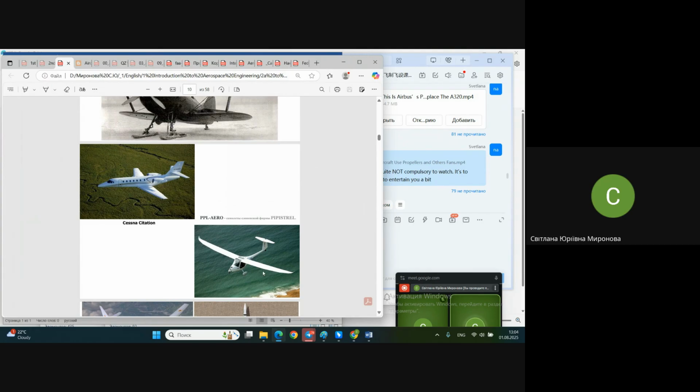How to increase the stiffness? Make the inner elements heavier. Make them more massive. Make them thicker. In case they are thicker, they are stiffer. But in case they are thicker and more massive, they are heavier. The circle is closed. In case they are heavier, we need more area of the wing, we need more fuel, and so on. So it seems it's not an ideal decision, it's a bad decision in this case to increase the whole stiffness of the wing.